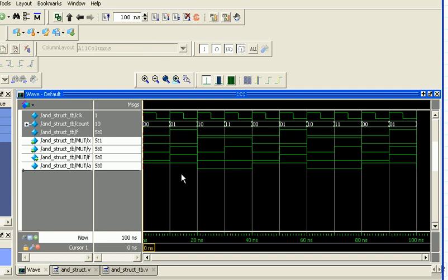So we can see that F is going to be 0 when the input is 0, 0. It's going to be equal to 1 when the input is 0, 1. So 0, 1 means x is 0, y is 1. And because x gets inverted, that is the correct result. Then when we have 1, 0, so x now is 1, and y is 0 actually, so that will produce an output of 0. If we have 1, 1, the x is 1, and so the x naught is 0, and that will produce an output of 0. So we can actually verify that this is correct.